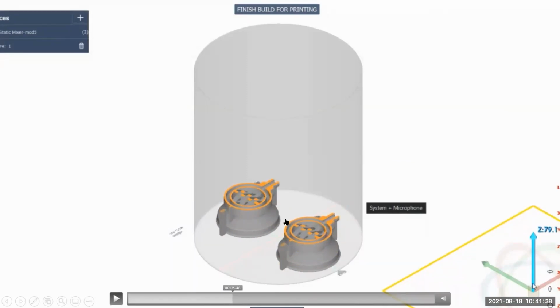This outer cavity here, something that's nice about having the inlets not supported is that when this cavity fills with powder during the process, you're going to need to drain that out after the build. So if there was support inside of this inlet and outlet bosses, it'd be obstructed, so you wouldn't be able to get the powder out very well. So having that free really helps a lot.